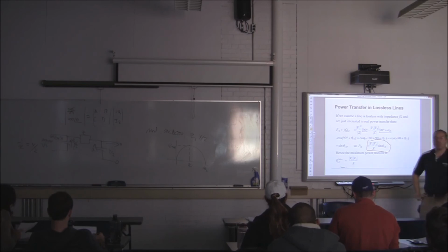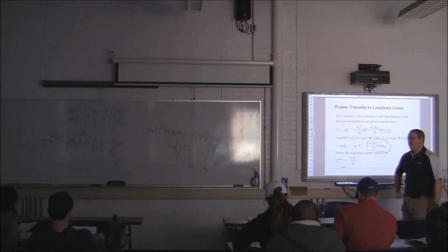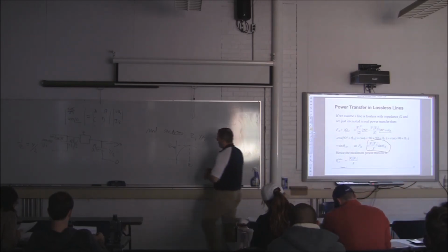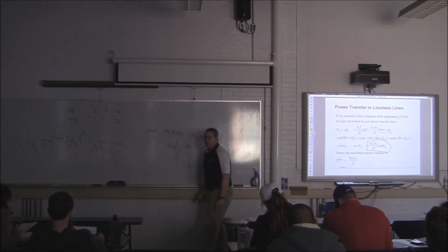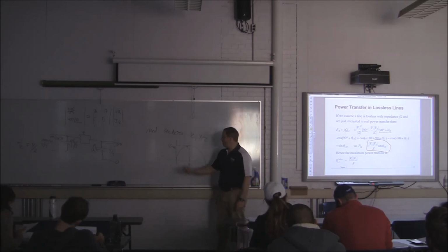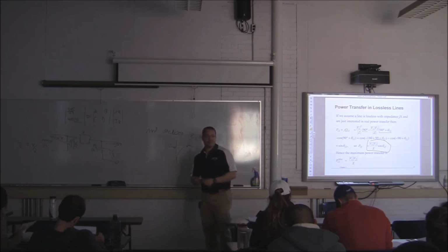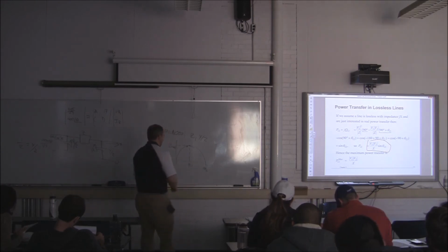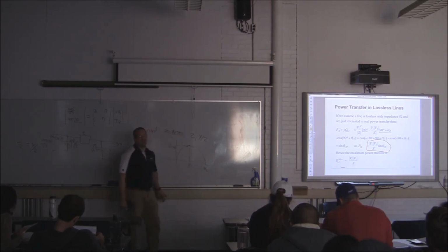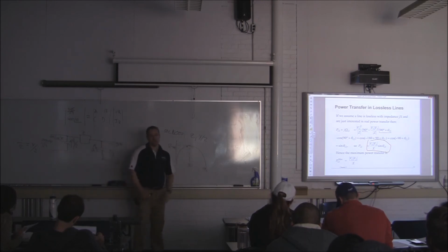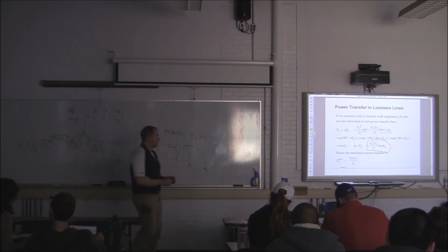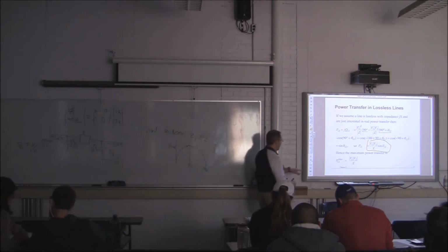We've talked a little bit about long lines being stability limited. That's because of this equation. And what happens if you run your line over here? Well, if somebody wants to increase the power flow, at some point it reaches its peak and then it actually starts to go down. What that means is your frequency starts to drop, and it is exacerbated if you can't get your angle back below 90 degrees. So at some point you'll lose synchronism. You'll actually go out of phase and you'll cause massive problems. Something you want to avoid at all costs.